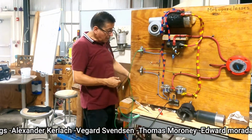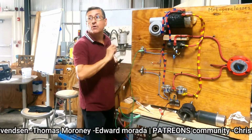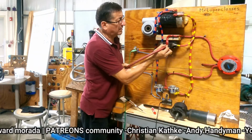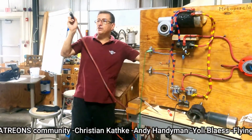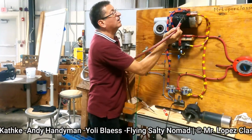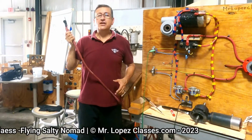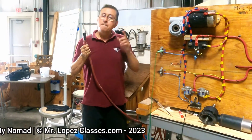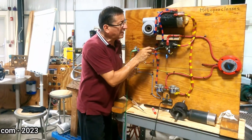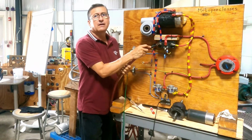This is the demonstration. Now, if I bring big current directly here or directly here, the motor spins. This one is connected to the positive of the battery, high amps, and the motor spins. Or here and here, no? Yeah? This is an indication that the motor is good, but the solenoid control box is damaged. If I bring the current here to the signal, nothing. But here, good.